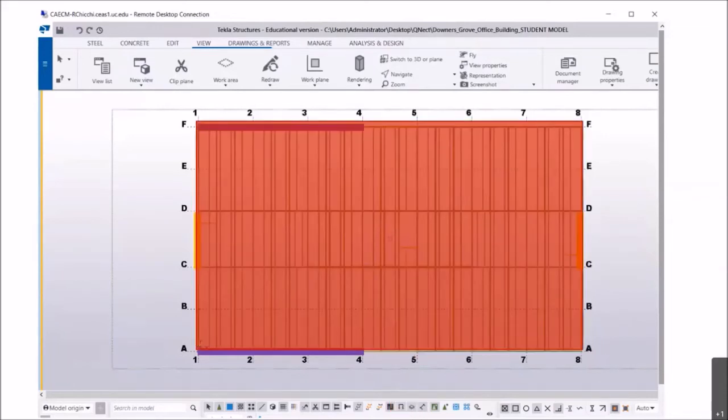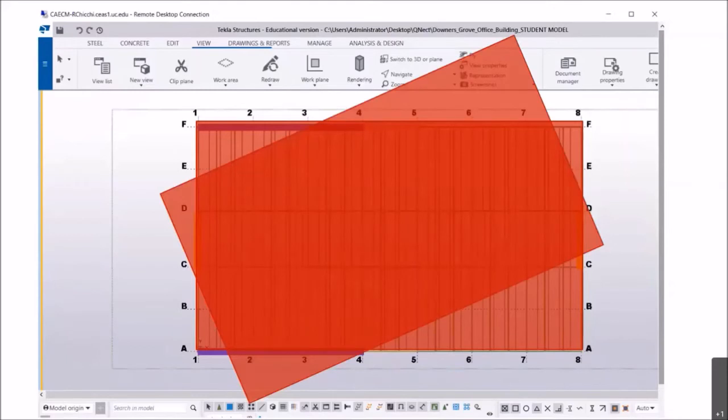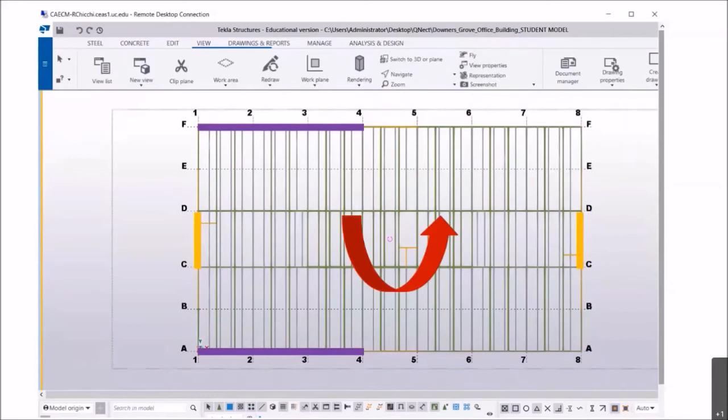So if we were to look at our floor plan and we're seeing some type of effect due to torsion, some kind of twisting of our frame, this would be related to this torsional moment. And how we resist that is by having these torsional shears in our frames. The further apart that we space these, the less force that they need to have because there's a larger moment arm to resist that torsional load. Also, by putting braces and deep moment frame members on the exterior, there are less issues negatively impacting the architectural layout of the spaces.